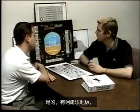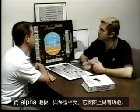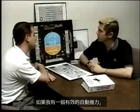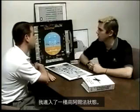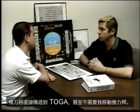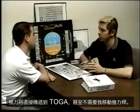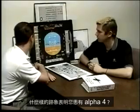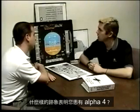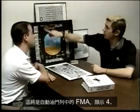Yeah, there's alpha floor. Alpha floor, as opposed to a protection, is really an auto throttle function. What that does is, if I have an operative auto thrust, I don't have to have it engaged, it just has to be available to me, and I get into a high alpha situation, thrust will go directly to TOGA without me even moving the thrust levers. And this is just a way to say, hey, I need thrust now. Okay, what kind of indication will you get that you have alpha floor? It'd be an FMA up here in the auto throttles column that says A floor.